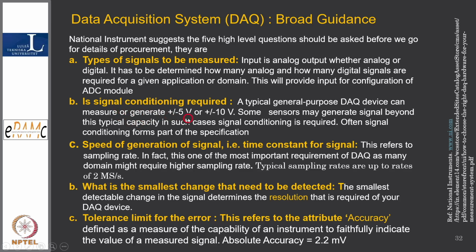Then, is a signal conditioning card required? This is a big question, because if it comes as a package and I don't need it, it is an unnecessary expense. At the same time, the physical matrix will also get disturbed, because when signal conditioning is not required, it becomes a load and liability on operation and maintenance. You have to maintain even this card, because the signal has to go through the signal conditioning card only.